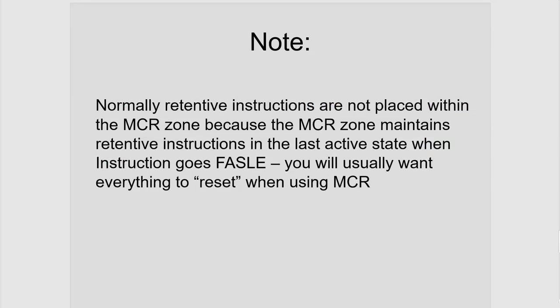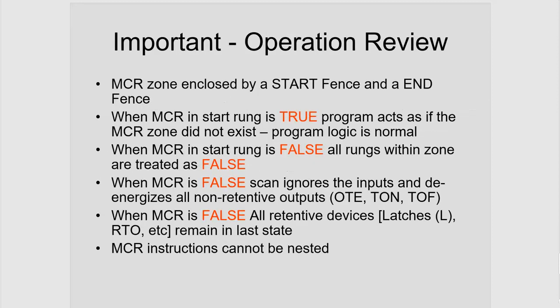And I think this slide deals with that, so I'll leave you to read that at your leisure. Now let's review what we talked about. The MCR zone is enclosed by a start fence and an end fence, and this terminology depends on the type of PLC that you're going to use. This is based on Allen Bradley, so they use the terminology start and end fence. But other PLC manufacturers will have something similar. The name they use might be different, but the functionality should be the same or very close.